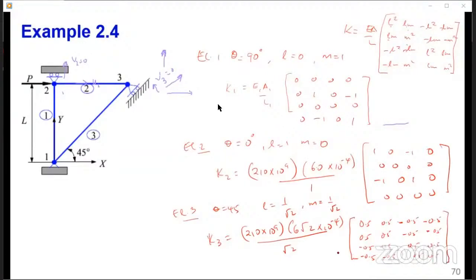Right. So you have it. You have the 3 equations. What you need to be careful to note is that when you come to the solution, know which node this is. U1, V1, U3, V3. Those are not to I and J. For element 2, this is U2, V2, U3, V3. For element 1, this is U1, V1, U2, V2.